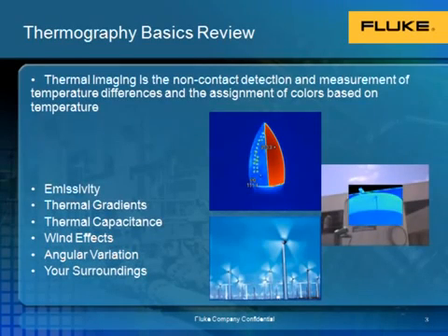As I mentioned, we'll start with a very basic review of thermography. Thermal imaging is the non-contact detection and measurement of temperature differences, and from there we assign colors based on those differences. As you see in the bulleted list here, there are several things to be cognizant of when using a thermal imager. First up is emissivity.